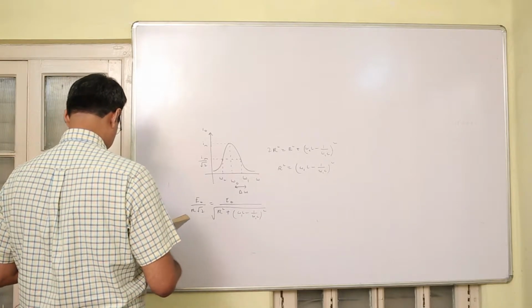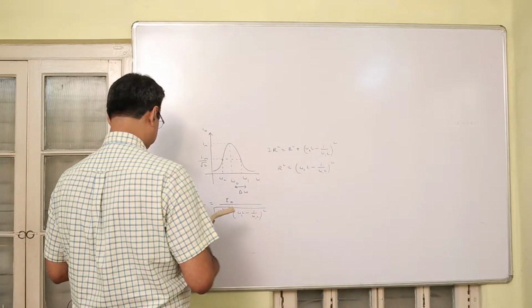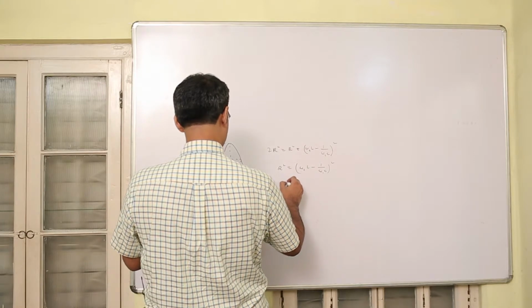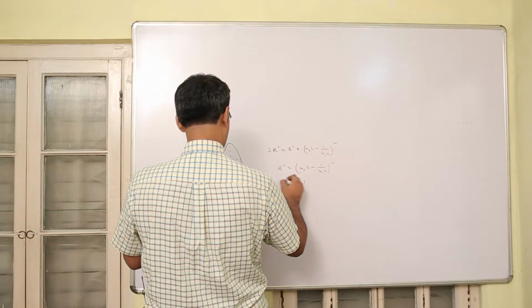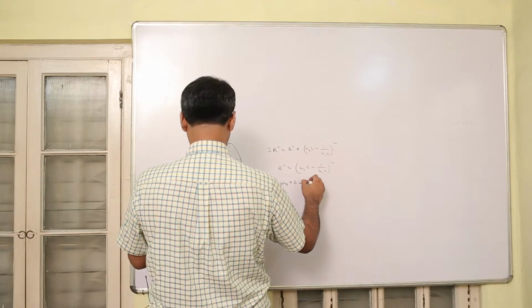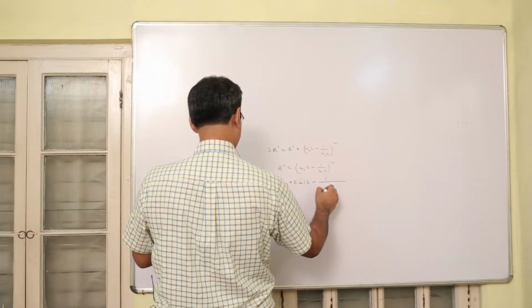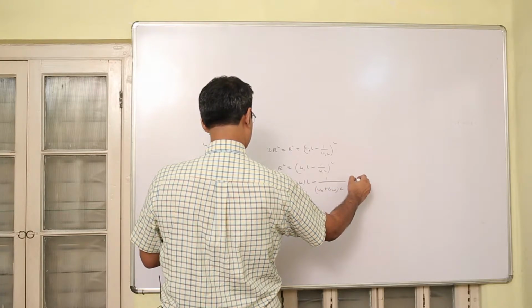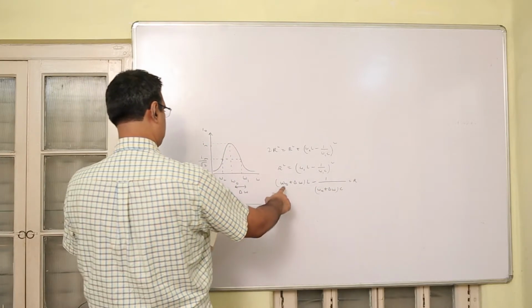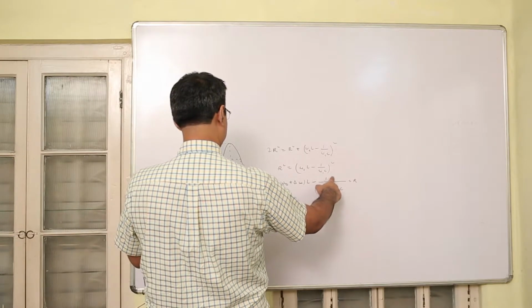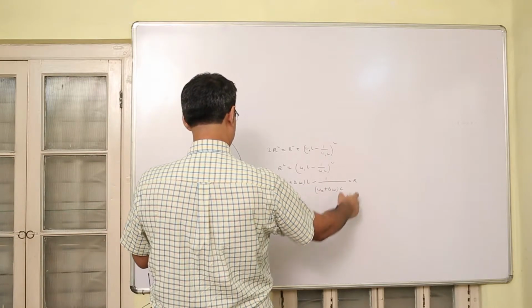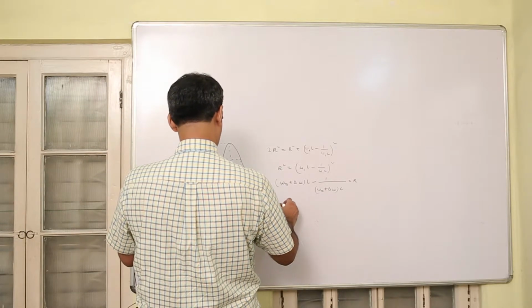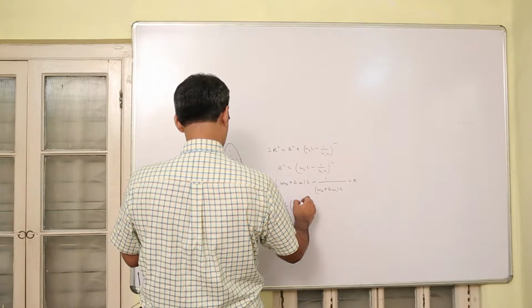Now using this expression, we will now write omega 1 as omega 0 plus delta omega. So we will get omega 0 plus delta omega into L minus 1 by omega 0 plus delta omega into C is equal to R. Now you take omega 0 into L common.